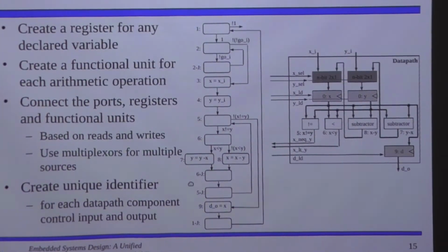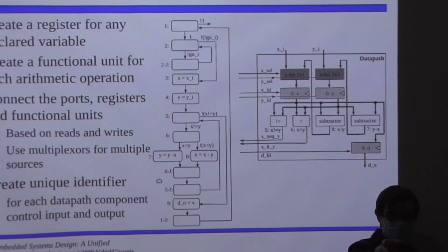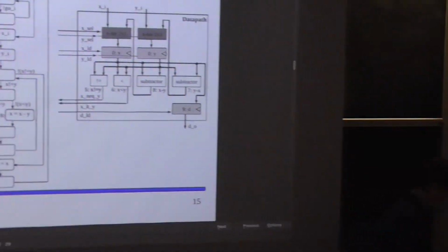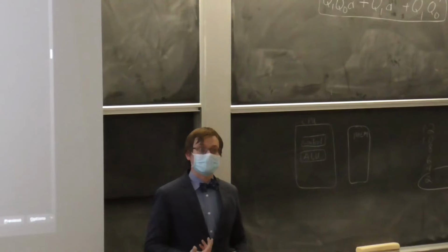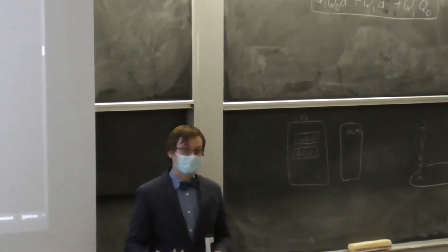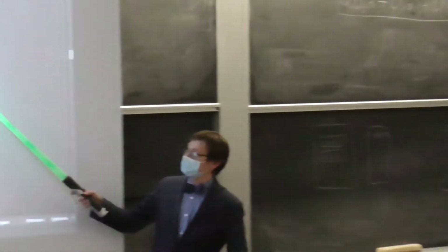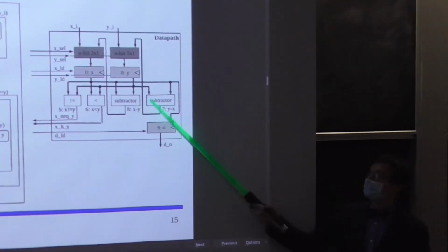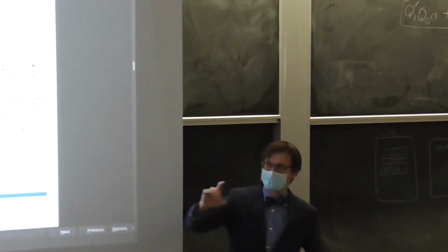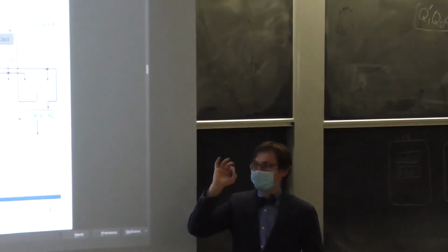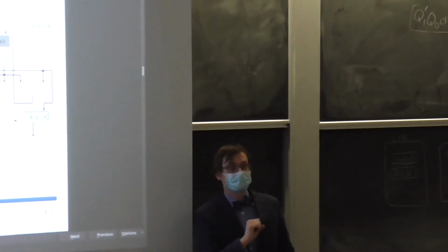I'm so glad you asked this question because it's a very interesting question. So for the purposes of the recording, the question is, what operations are actually in the ALU, given that the ALU is made of these operation blocks and multiplexers? And the answer is, roughly speaking, with a couple of exceptions, the instructions of your assembly language, right?